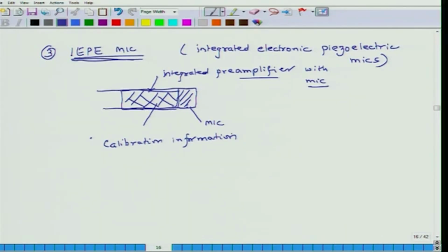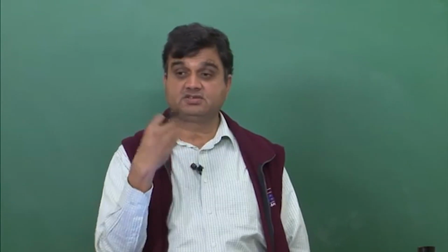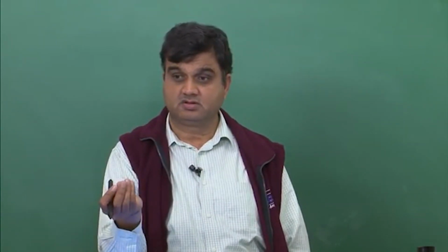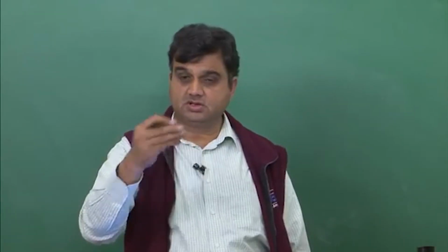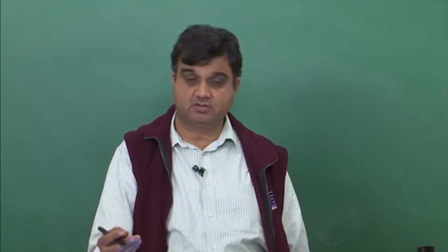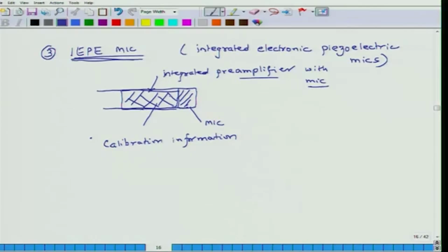So the signal which you will get will be directly interpreted as pascals. You may not have to convert it into volts using your minus 20 sensitivity level and all that stuff. You may get directly pascals. So this preamplifier may already have a lot of calibration related information.